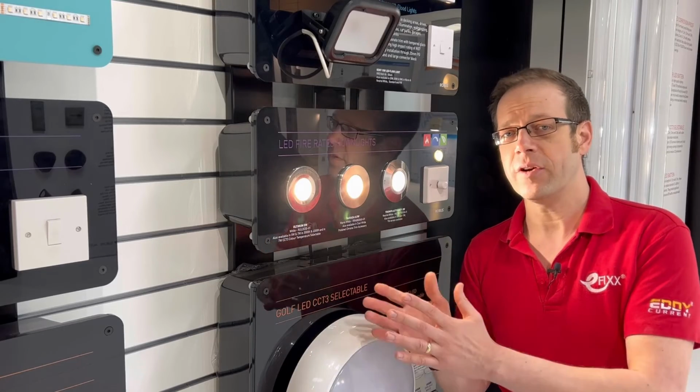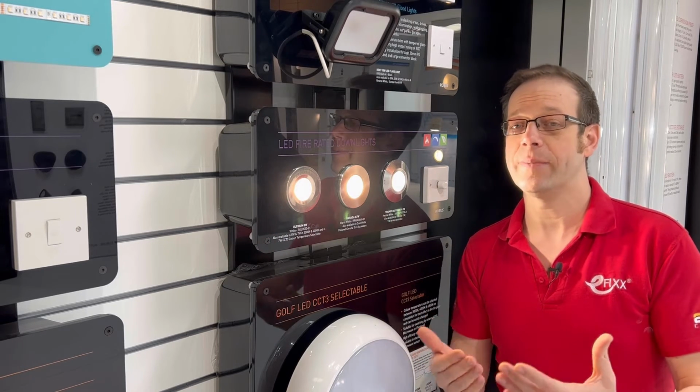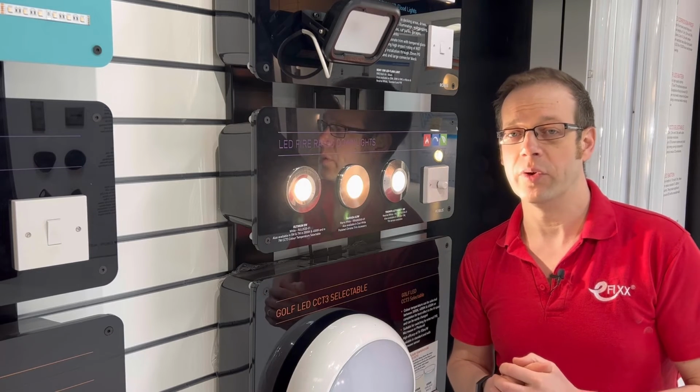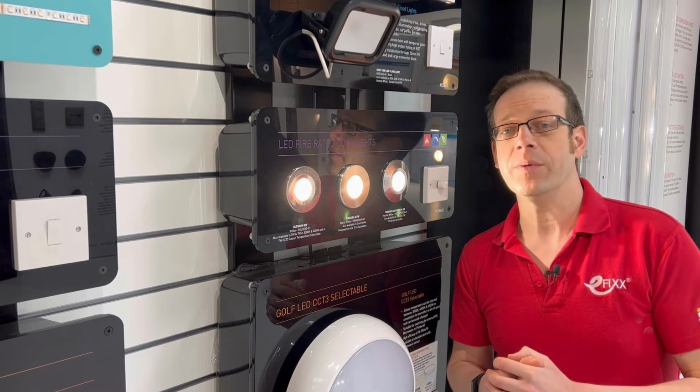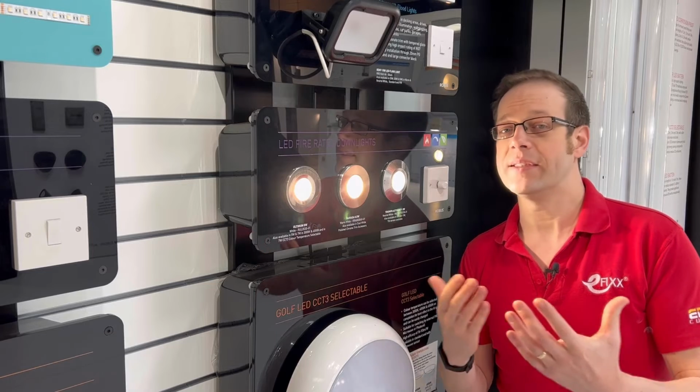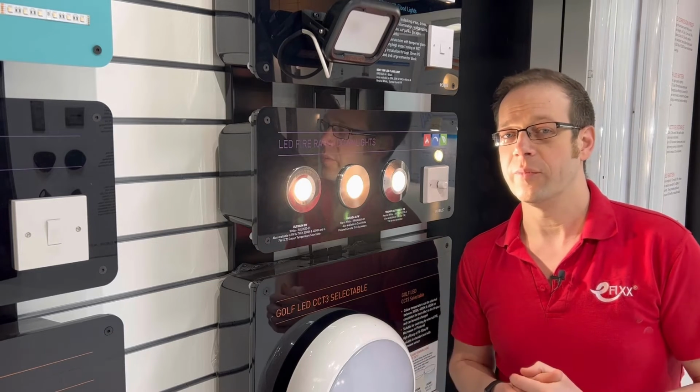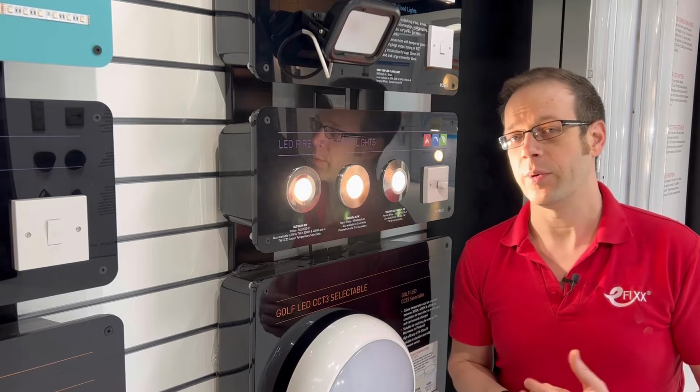It's important that the correct fitting is used in the correct environment, as a light fitting in someone's home is likely to be used less and to be in a cleaner environment, as people tend to care for their homes and property more than they do at work. Also, a fitting designed to be installed into a ceiling tile is not likely to have been tested and approved for its ability to prevent the spread of fire in a property.